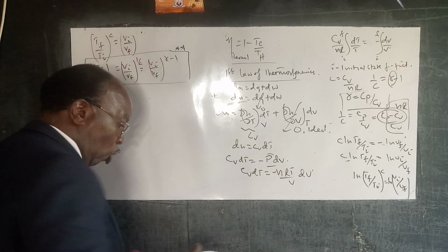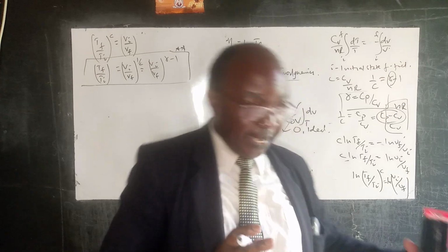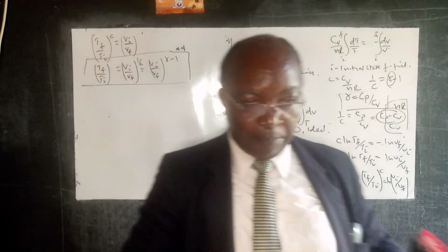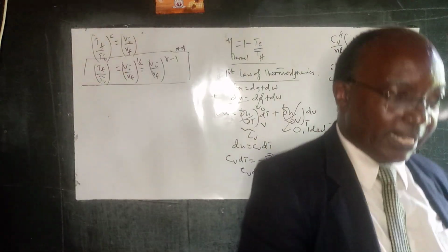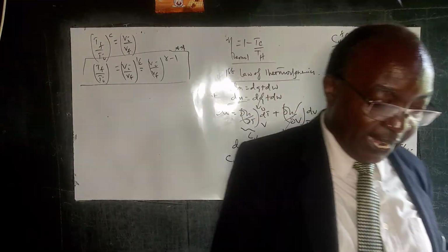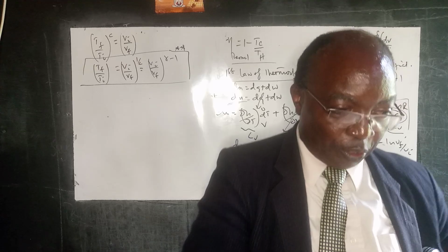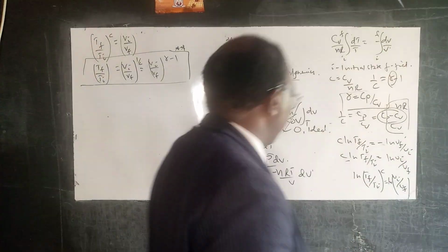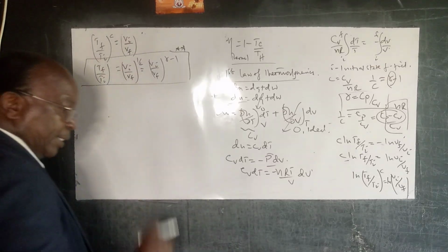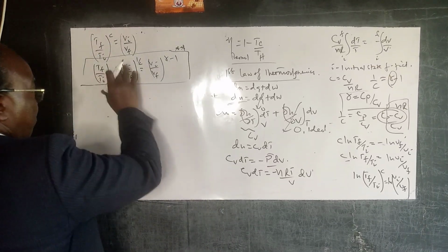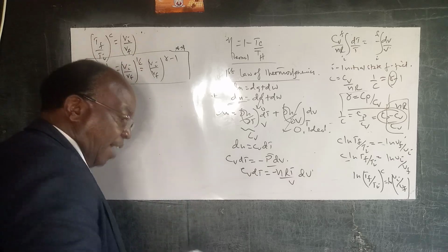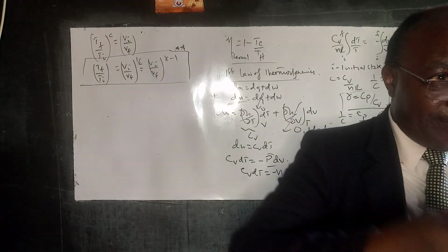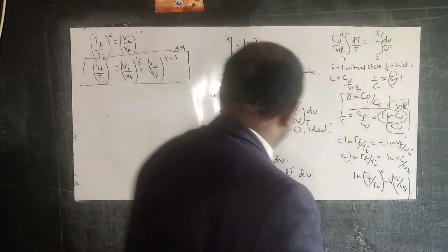So let's now focus on those processes in the diesel cycle where work is done. Work is inputted in the compression process, when you're compressing the gas. When you have expansion, work is done on the piston, pushing it down. So those two processes, we have work input and work output, and then we have that portion 2 to 3 where we have the ignition, where the fuel is injected into that compressed air.